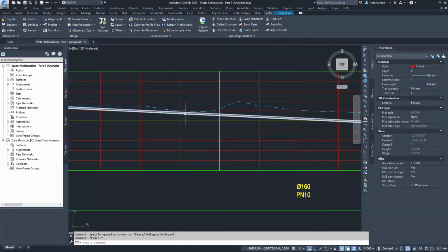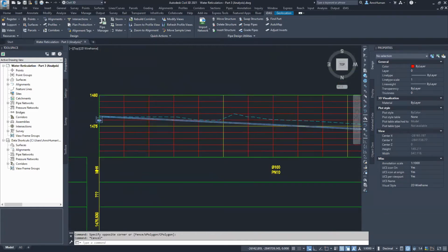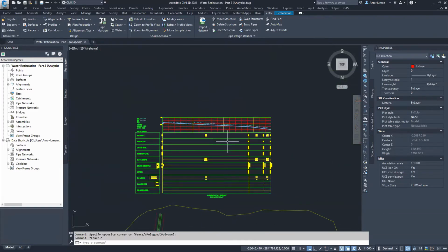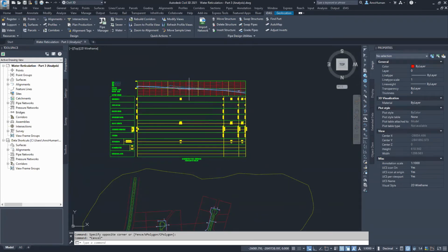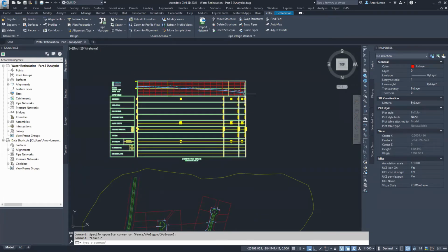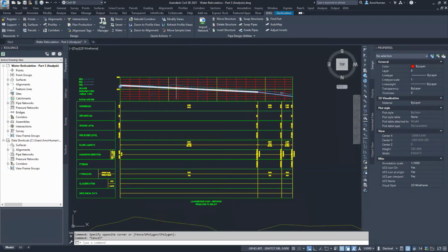Now, I can see some parts where I can adjust for cover, but you would do that exactly the same as what I've shown in the bulk water example, where I insert a structure, choose a cover, and add a junction over here. That would add a vertical bend fitting for us, just so that we can achieve cover, right? So it's always good to check some parts of your network to make sure that you have adequate cover. Once again, the reason for that is because cover is only measured at the start and the end.